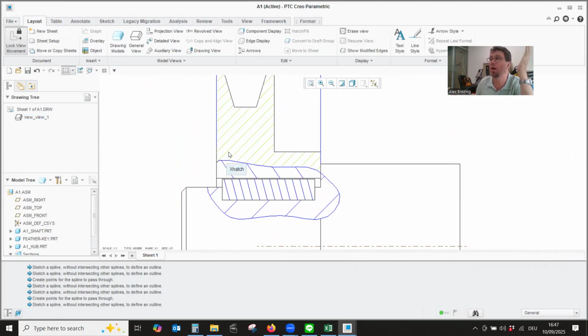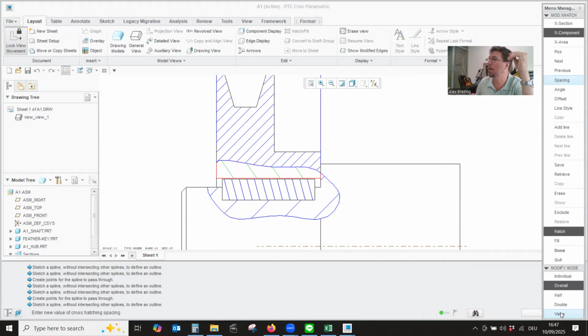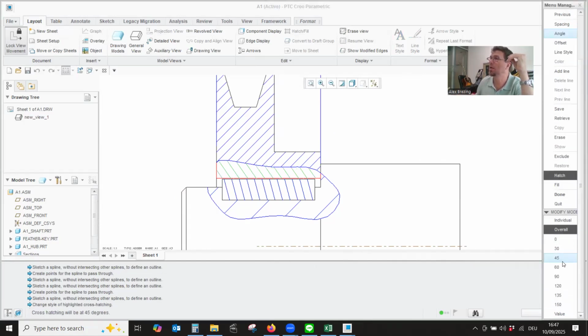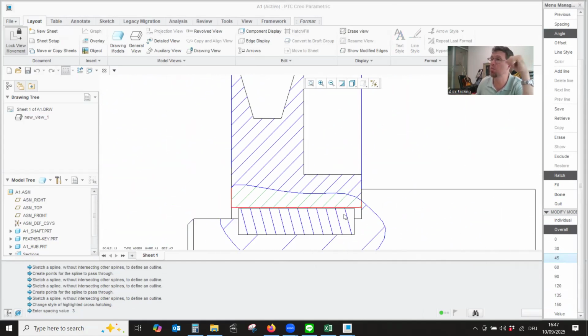So just make sure, see, these are two different sections. So these are two different hatches to highlight. So I'm highlighting this second one. I double click it to change the properties. Now it's highlighting the hub, and the best I can do is just give it the same hatch as I used before in the main section. So I give it the same value and the same angle. And you see, it's actually perfectly aligned. This is one good thing. It remembers the position of the hatch.